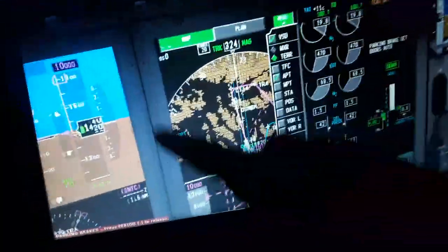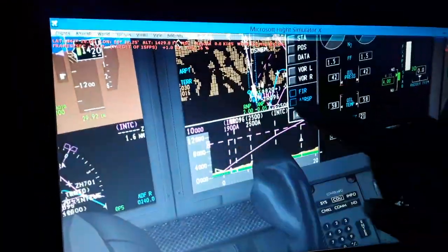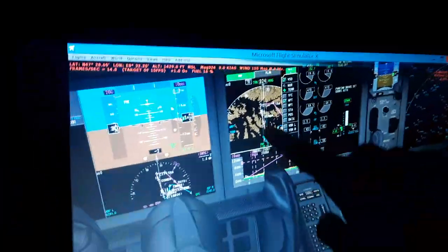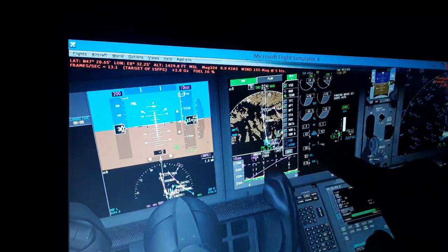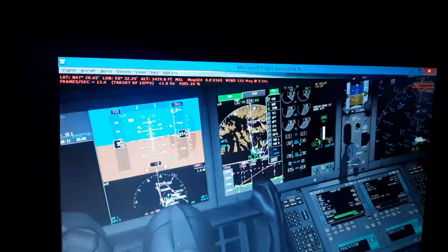So also in the navigation display, we have the vertical profile of the aircraft for climb and descent, and the terrain in the vertical profile. You can see over here we have the horizontal profile of the navigation display and the vertical profile of the navigation display. You can see the flight plan with this purple line from takeoff, climb, cruise, descent, approach, and landing. Also here is the climb. You can see also the cruise and the descent part of your flight plan. So we have a complete flight plan or route or flight path for the aircraft to fly, which we created using the flight management computer.